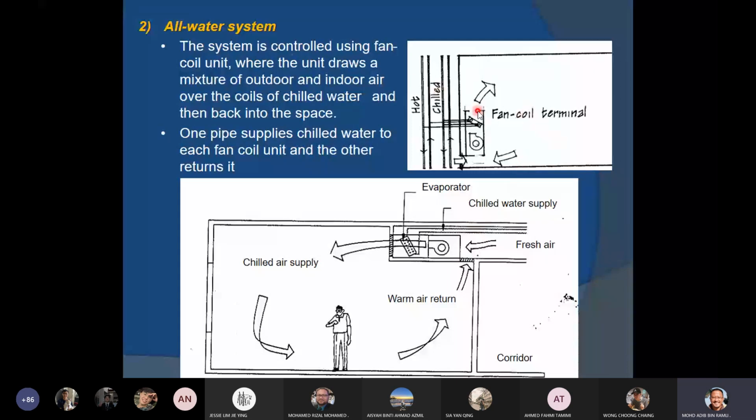So this fan coil unit, basically here you can see the pipes, right? So these are chill water pipes, okay, from the chiller directly delivered to the spaces. Then what happens in the space, basically, it gets the proportion between the chill water and hot water to get to the desired temperature, right? So what's inside the fan coil unit is basically the fan.